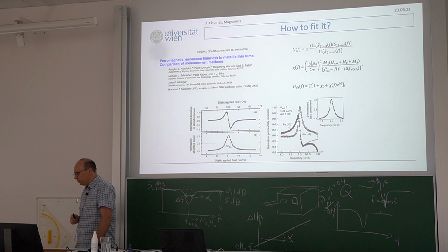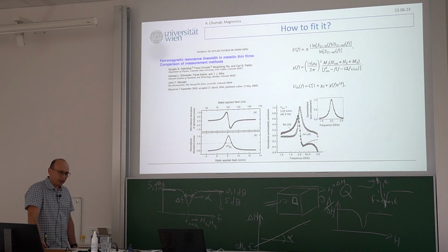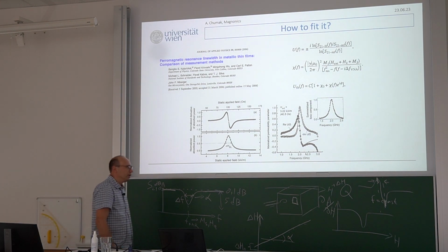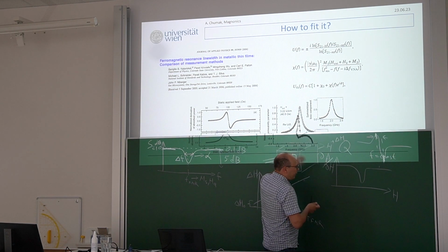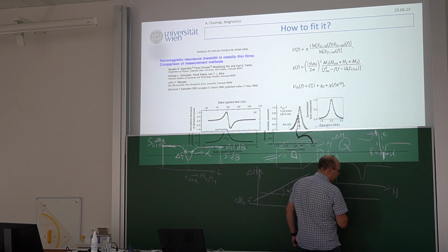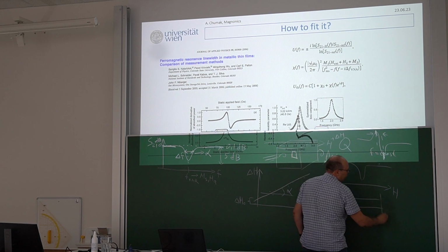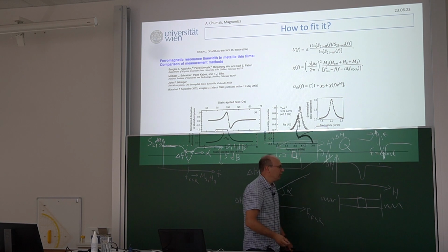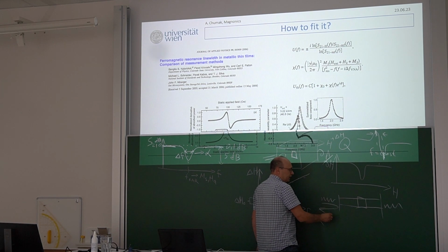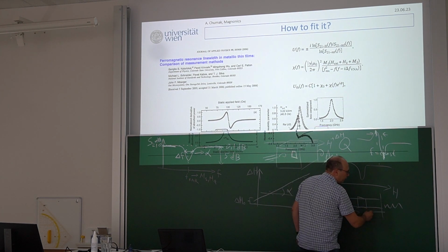So if you see a weird peak, just pay attention. If you check the literature, there are many other papers. There are many experts in the field building different theories. For example, if you have your microstrip line, here you have some connector, some adapter to coaxial line. And here's the coaxial line. Then there will be some sample. So you always will have some reflection here. You will always have some reflection from the sample, also from the opposite direction.